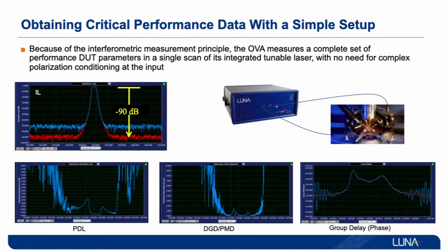One other quick key here is that just measuring the filter shape of this type of filter, or really just measuring the loss of any high-speed device, is definitely not enough to characterize the device. To really characterize what the effective bandwidth of this filter is, you need to measure all of these parameters and how they work in concert. As an example, we're working with a customer right now that was seeing huge variations in the EO bandwidth of a new 25 gig design.